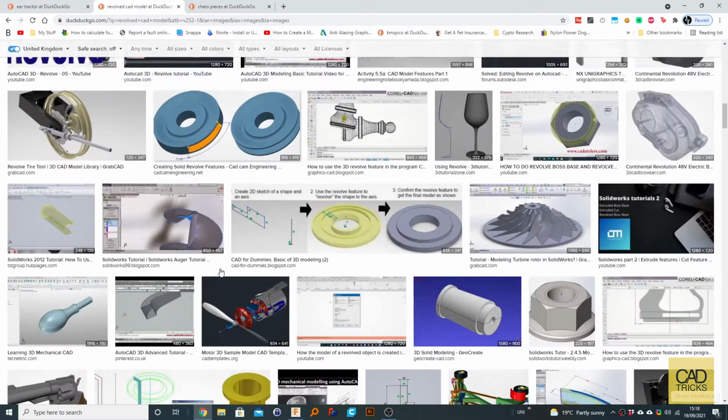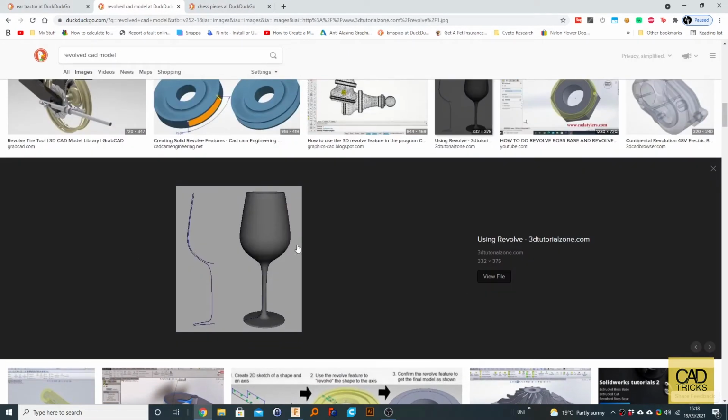Another example, this wine glass, you could make all with the revolve tool. We'd make half of it, the outline shape here, and then we'd spin it. You can see here, this is the profile that was used to create this shape. For some reason it's missing the right edge here. These two should be connected, and then we should revolve it around the center axis, or the origin. Obviously the top piece here, once you revolve it, should be empty based on the profile.